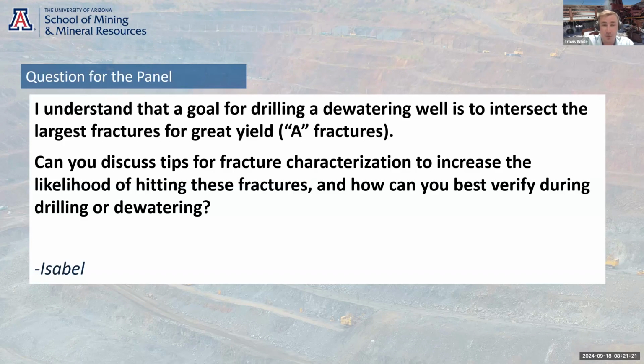This is particularly difficult when you've got vertical or near vertical structures, right? And especially if you're drilling through some overburden. So it's good practice to spend a bit of money on some of the ground truthing on the geophysics, just to get the orientation in terms of which direction the structure is dipping, so that, to link back to what Jeff said, you can hit the structure at the right depth.